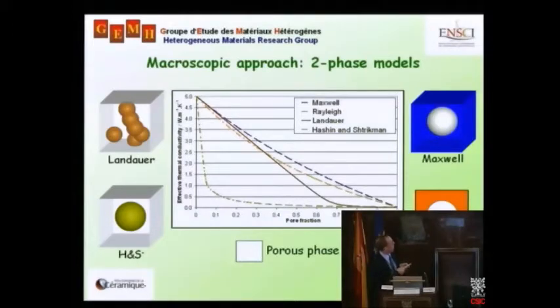Now there's another very useful model, because when we make typical ceramics, if it's very dense, the porosity is closed, but if it's more porous, let's say 50%, the porosity becomes connected or open. So this model would no longer seem to be appropriate. For this situation, Landauer's effective medium expression is rather useful. This is based on taking equivalent pore volumes plus grain volumes of equivalent size and mixing them up with random positions. Okay? So this enables us to go to a situation with open porosity.